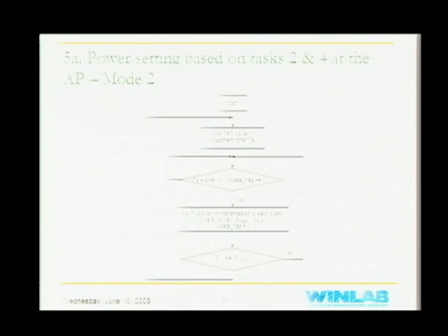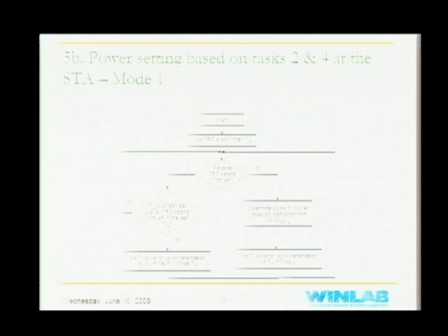So we always choose to use the maximum of the 2, because PRSSI also serves as the reference for PFLR. As we already said, that's the transmit power which we use as reference to either bump up or bump down. So whenever the update flag has been set or whenever the TPC timer expires, which is every 1 second, we effect a change in transmit power, which will be the maximum of the 2.